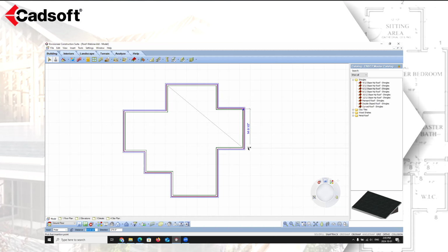I want this to be a covered porch. So I'm going to create a line using my snap tracking tool to know exactly where I want this roof to sit. And then same over here, I'm going to use my snap tracking tool to again add in my roof over those points. This will create the roof, but now it's going to be going over top of certain areas instead of going over top of my walls.